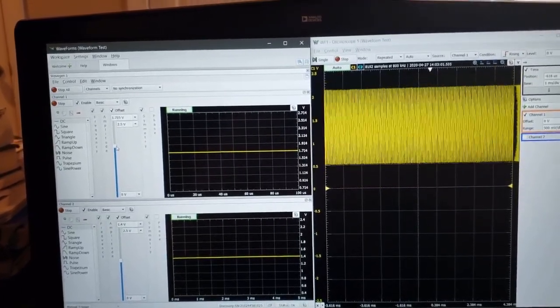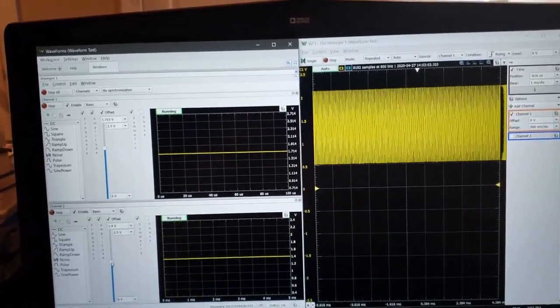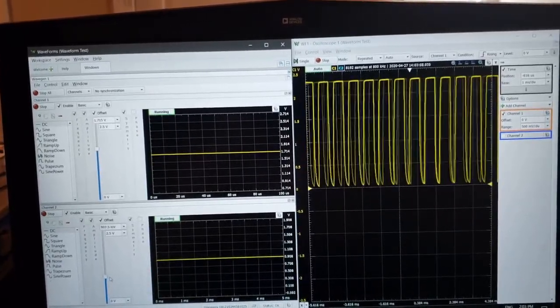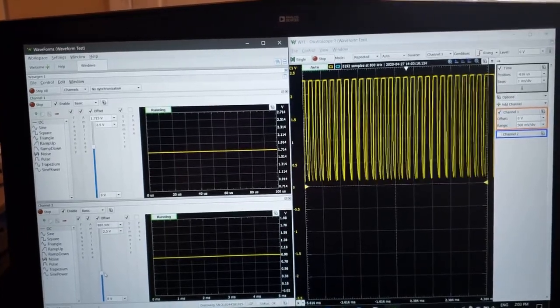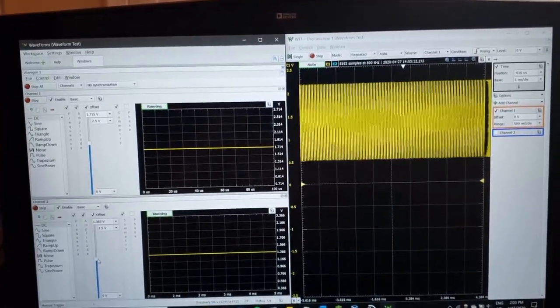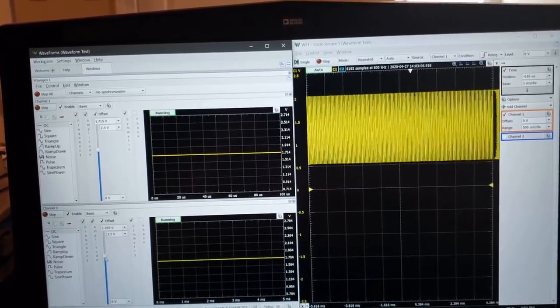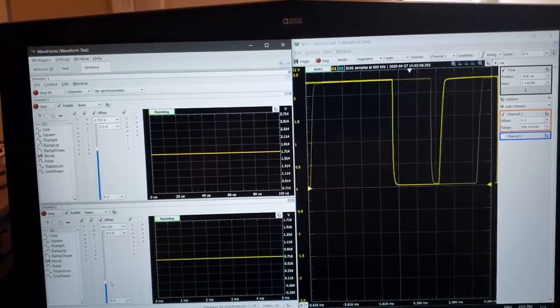As the PFET bias voltages for the CSIs were decreased, the square wave frequency was increased and the amplitude was decreased. As the NFET bias voltages for the CSIs were decreased, the square wave frequency was decreased and the amplitude was increased.